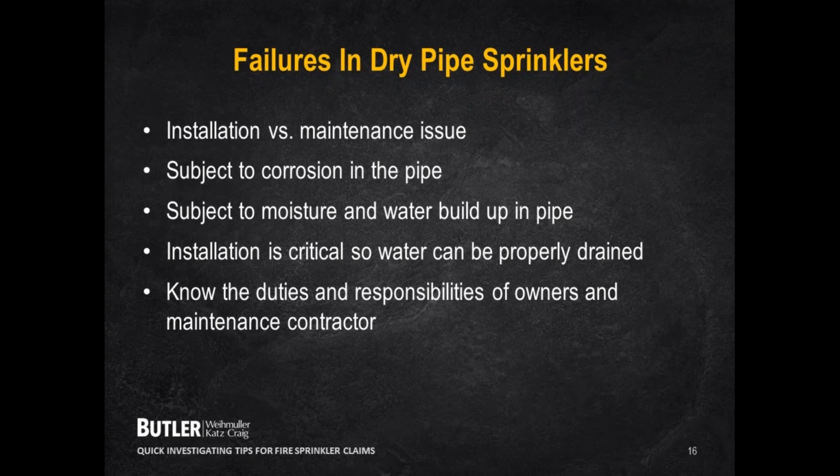So some of the things to look at in the dry pipe fire sprinkler claims is the installation is critical, like I stressed previously, because if the installation is not right, the water will not evacuate from the system after it's tested.